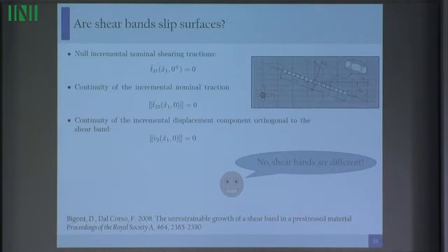So shear bands are a sort of sliding interfaces, but actually they differ because the shear bands are assumed to follow these rules, and these rules are not corresponding to the slip conditions I have shown before, but let's say they look like the wrong conditions. And these are the conditions which occur at loss of ellipticity in the incremental response of an elastic solid.